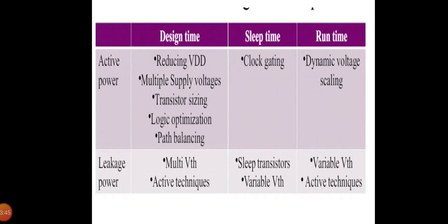So the sleep mode of operation deserves special attention. If a digital block receives a clock while in idle mode, the clock distribution network, together with the attached flip-flops, continues to consume energy even when no computation is performed. You can recall that typically 1/3 of the total energy of a digital system is consumed in the clock distribution network. A common method to reduce the power in idle mode is the clock gating technique, which was introduced